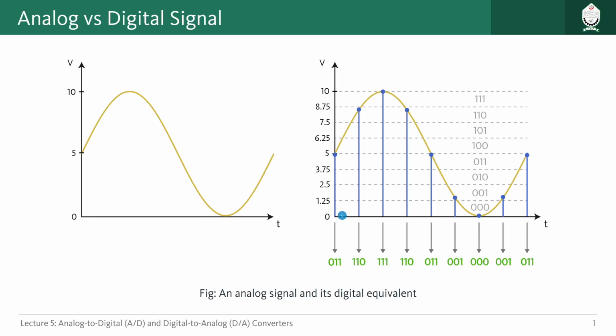Through a process we will quantize the time direction such that after a finite time interval, we will sample the voltage, the amplitude of our analog signal. You see, after this amount of duration we are taking a sample of the signal. In this way, after going through the process, we have discretized the time domain, right? And this is what we call sampling.